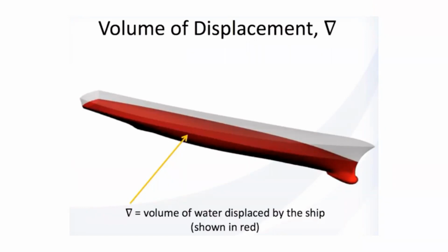The way we did it for senior design is that we create two models of the same AUV that we're using. One was solid, with all the dimensions and properties of the materials that we need. The other one, we changed all the properties to salt water. So all the components of the second design had the density of the salt water.